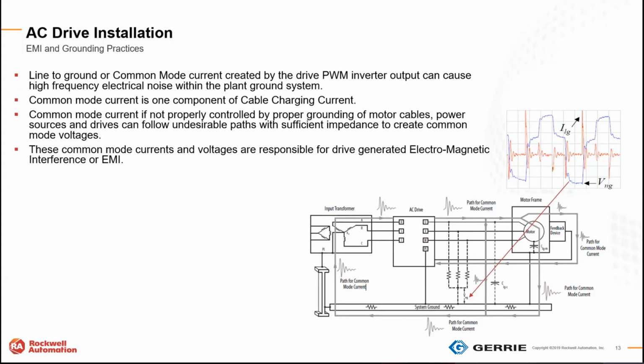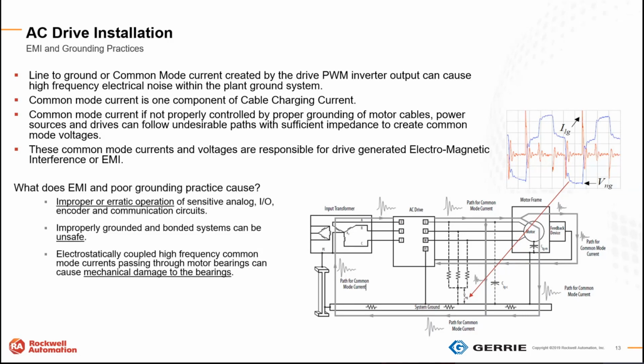Some of the other things we run into as well is EMI and grounding practices. We may have issues where customers are complaining that the drive is interacting with other pieces of equipment, causing erratic operation or other issues, usually analog equipment, anything analog, metal detectors. It tends to play havoc with those as well. And typically, the way that we can get rid of some of the nuisance ones is just to properly ground the system.